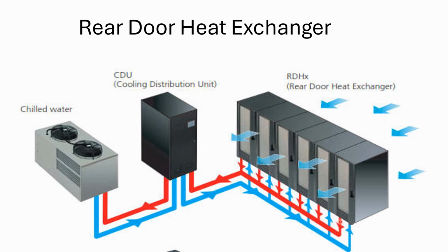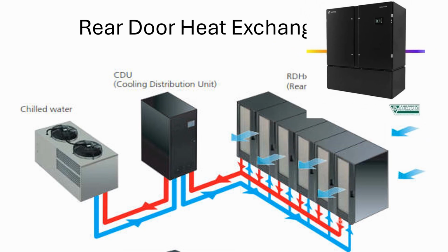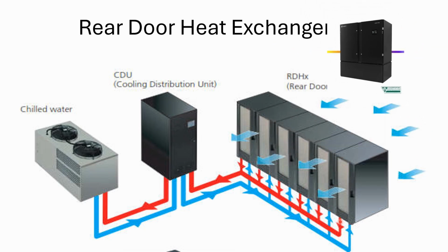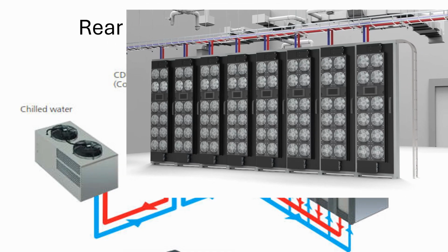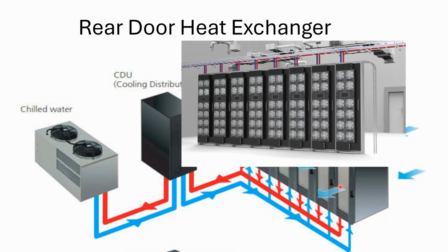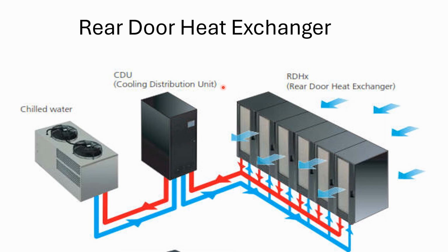It is basically required where we have an existing setup and the air handling units or air cooling systems are not capable of handling the heat load, without disturbing the IT hardware. If the temperature of the air is very high when it passes through the servers, it is pre-cooled by the heat exchanger before entering the existing setup. So this is the basic of the heat exchangers.